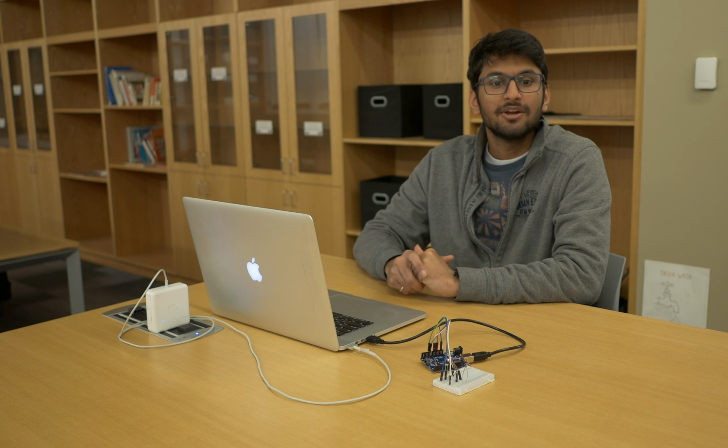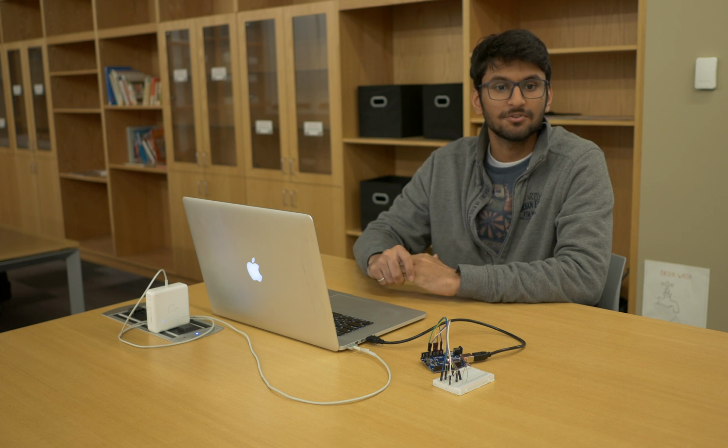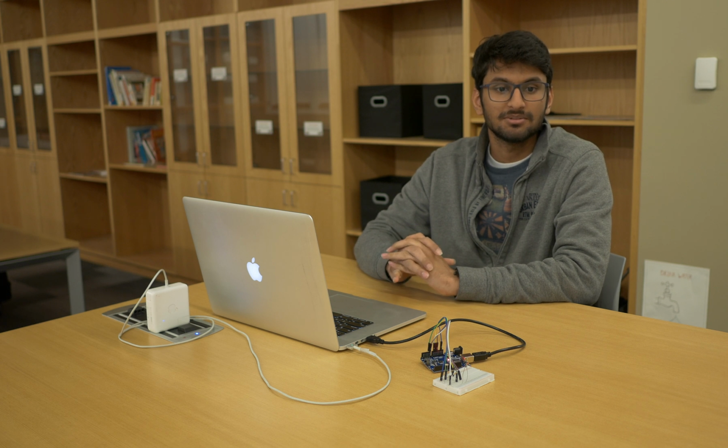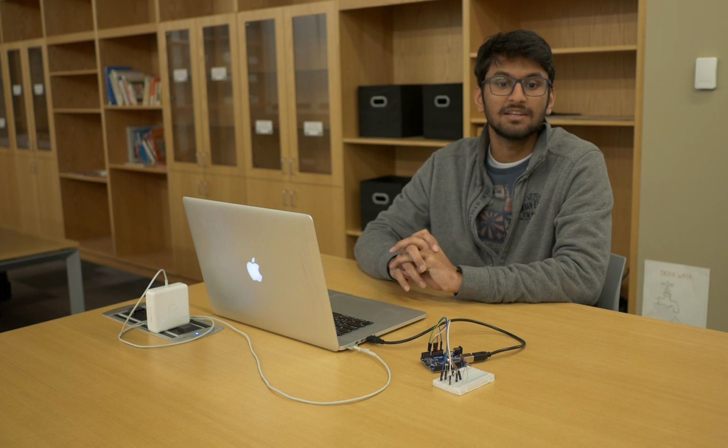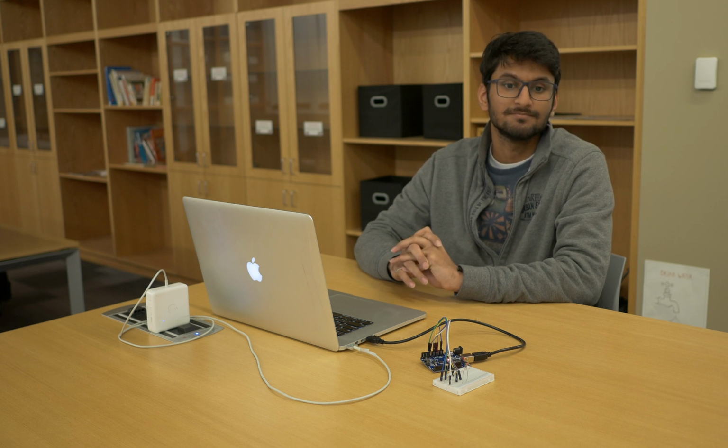In this project, we are using a voltage divider in Arduino using Matlab to display raw and calibrated data for a thermistor. We are also displaying the resistance of an attached photocell. Both of these data sets are displayed in real time on a single graph. The thermistor graph displays the temperature based on a linear approximation, temperature based on a Steinhart model, a running average, a thermistor resistance, and finally the difference between the two temperatures.